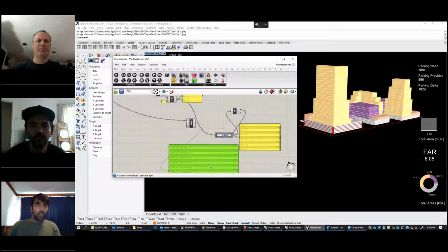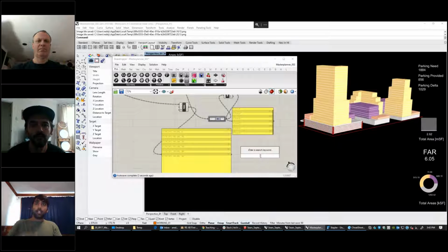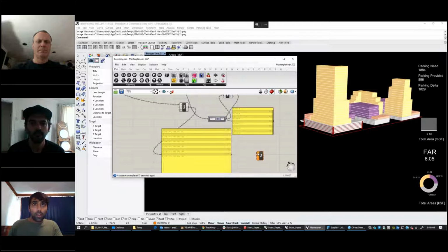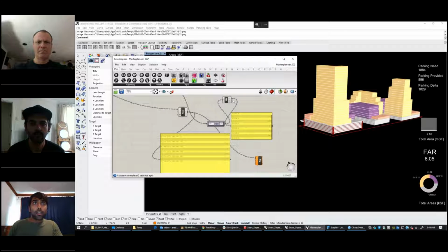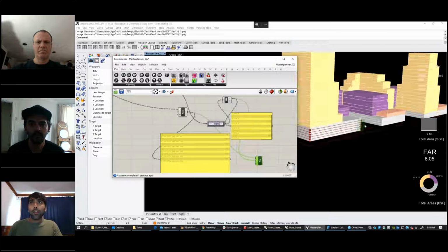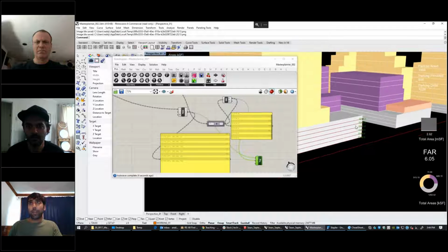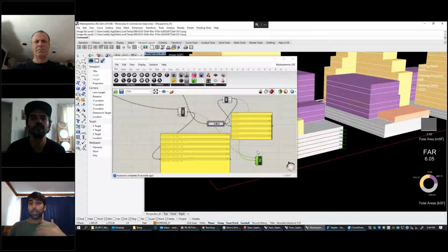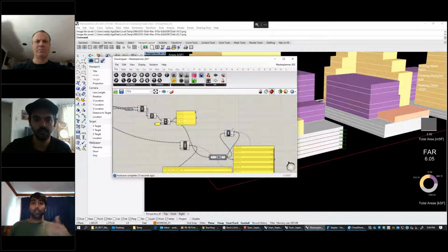It's going to be 0, 1, 2, 3, 4, 5. This is why that tree branch management is important, is you can do a text tag, right? A 3D text tag maybe, or a text tag in your Rhino viewport. So your location is going to be your points, and your text will be your mass addition numbers. And now you've got your floor by floor numbers right there, live on your model, right? So things like that. It just depends on your project, what you're doing, how you want to count your numbers, but just thinking about it in that way, that you can be creative with the way you want to break it out. But it's all just tree branch, tree management, understanding how that works.